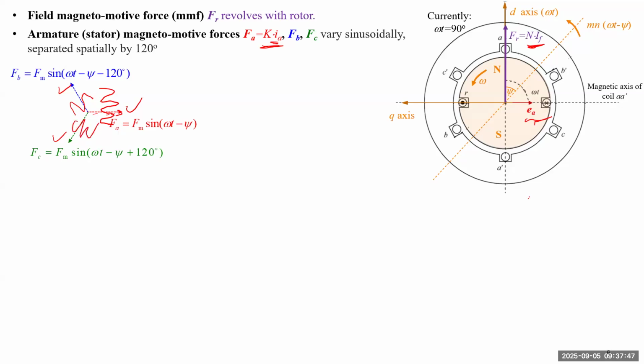So there are 3 directional phasors, and the length of each one will change periodically. We have to formulate each one, then calculate the total magnetomotive force. Together they become something we call FS, the stator winding magnetomotive force. We don't want FS to be too complex because we're going to need FS together with IFR to determine EA, the phasor for the stator winding A.